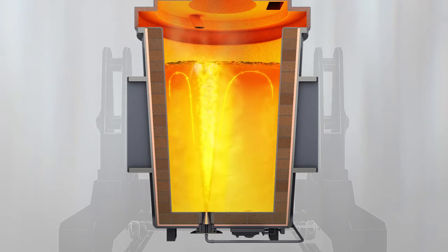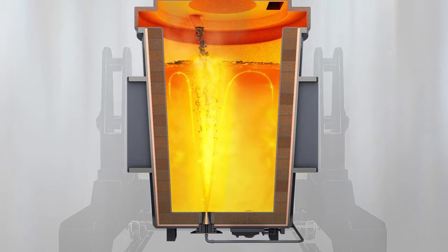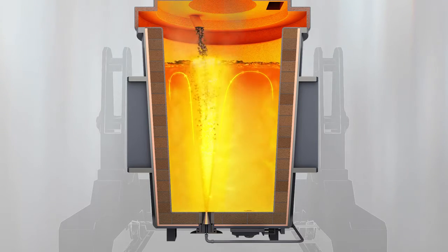The ladle is usually constantly stirred during secondary steelmaking, as this facilitates the dissolution of the ferroalloys being added. But if the stirring is excessive, creating turbulence, smaller lumps move up and come into contact with the slag, and their alloy contribution can be lost through oxidation.